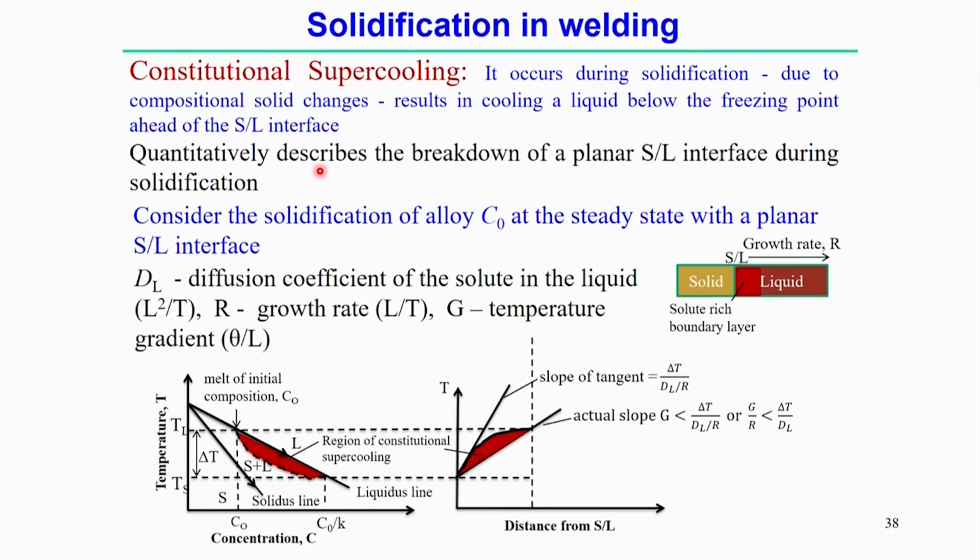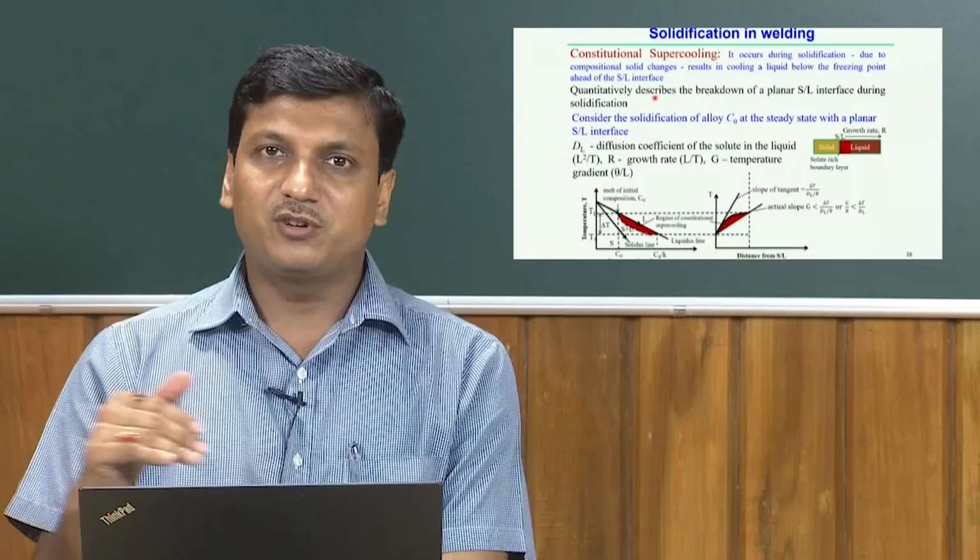So, during that transformation, there is an amount of supercooling observed in the liquid metal. Of course, it pertains to some conditions, that means before the start of the phase change, the nucleation mechanism involved in the welding or solidification process is governed by the amount of the supercooling temperature, that means the temperature below the solid to liquid transition temperature.